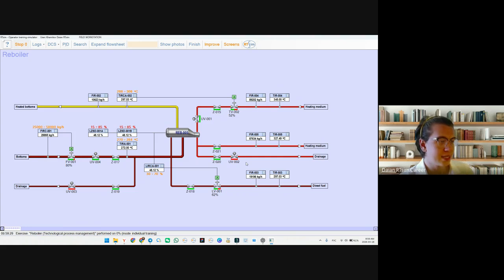It is very important not to leave the hot circuit, in this case the pipe space, without cooling. Therefore, the degree of filling of the heat exchanger is approximately 15% here. This is an emergency. That is, if the level falls below this space, the heat exchanger will overheat and possibly break down. Accordingly, 15% is the emergency level.